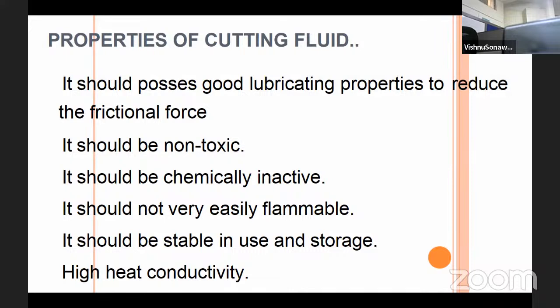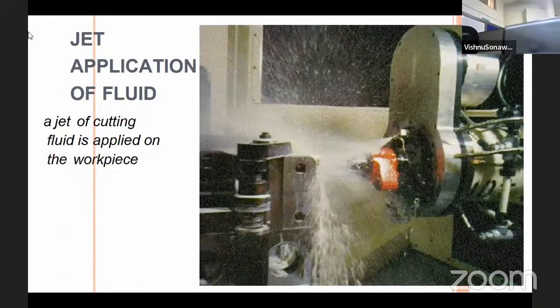These are the most important properties of cutting fluid, and if we maintain all these properties, the cutting tool life will automatically increase more and more. This is the jet application of the fluid. The jet of cutting fluid is applied on the workpiece, and it should be directed through the nozzle at the point of the cutting tool interface and the workpiece.